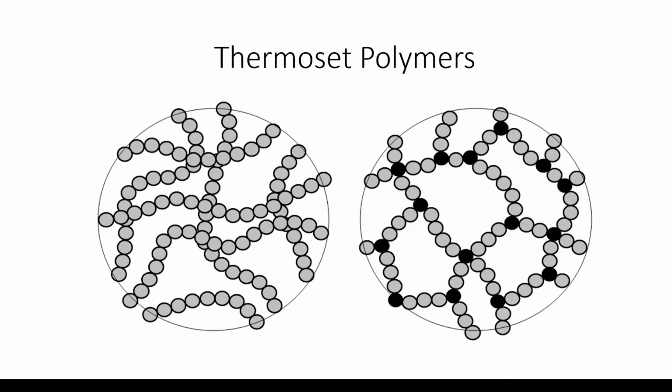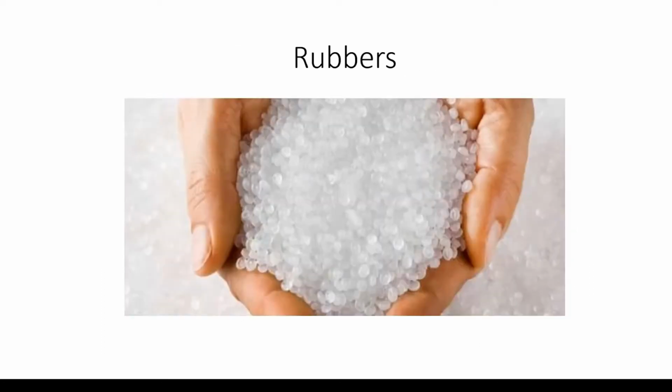Thermoset polymers imply thermoset plastics. They are distinguished by the fact that during processing they are cured and form 3D networks. They are described as long thin molecules laid in a random manner with no firm bond between the molecules. During the curing process, permanent bonds are made at numerous points in the chain with other molecules. So, next one is rubber.